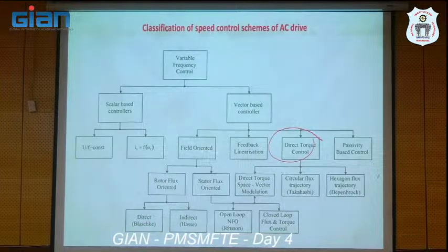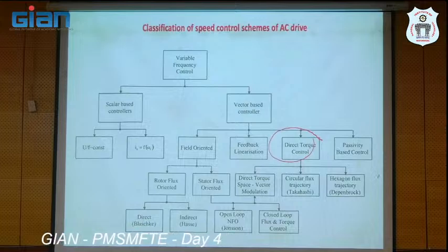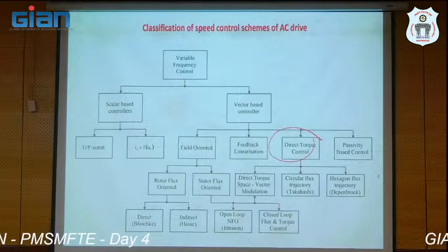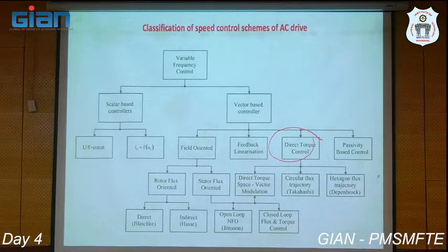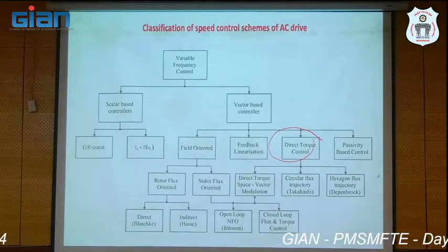Why? Because transformations are there, too many calculations, as in indirect field orientation. A lot of calculations are required to get the rotor flux position, right? So the next important thing is the rotor flux position estimation method.